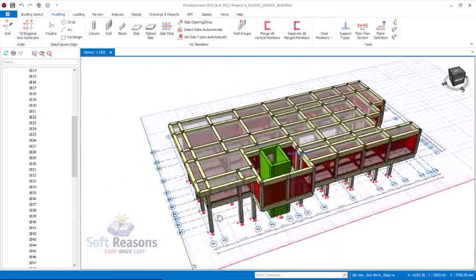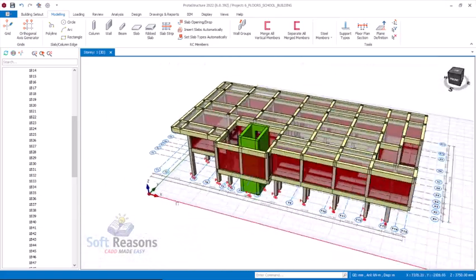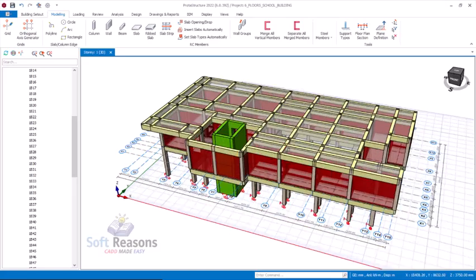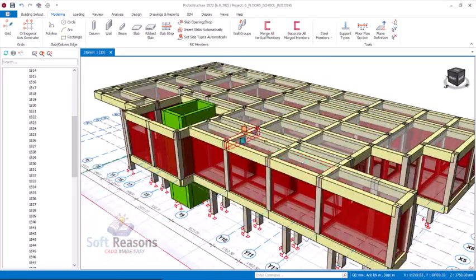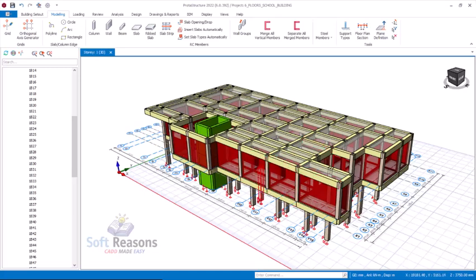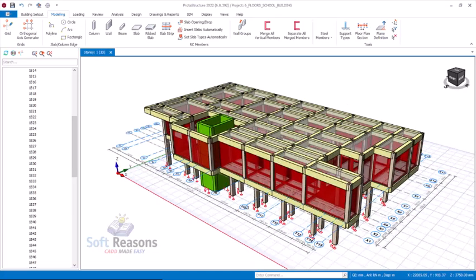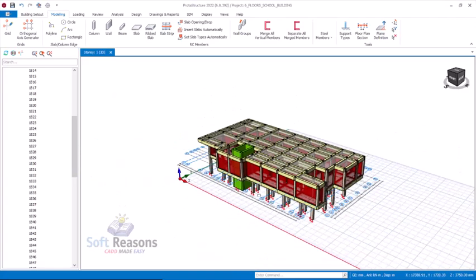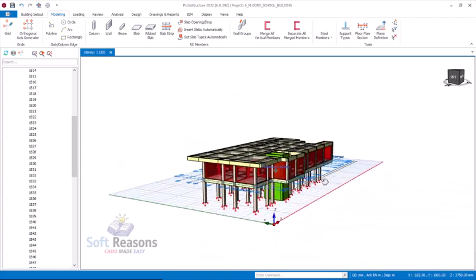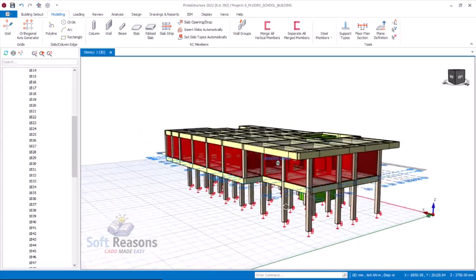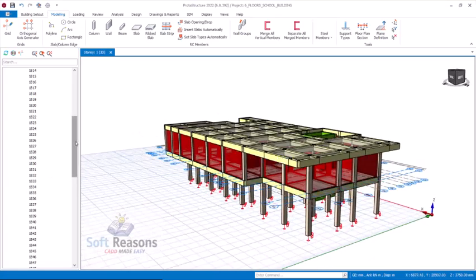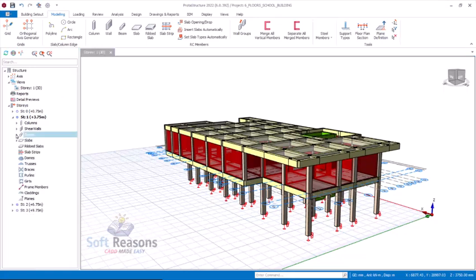So we are going to be generating this particular first floor, but as well you can still place loads here before we generate this floor to the next floor successfully, or we can generate before we place the load. Whichever way you want to do, you can do that successfully. So we have already inserted 3 floors.